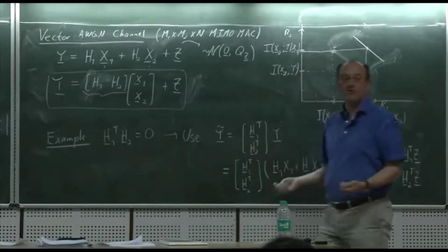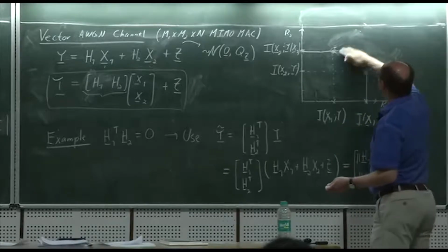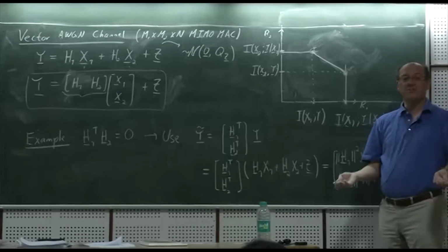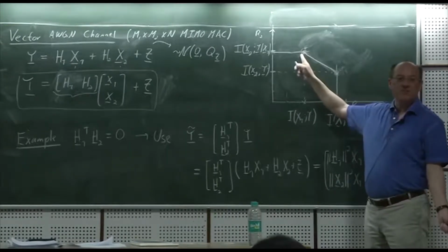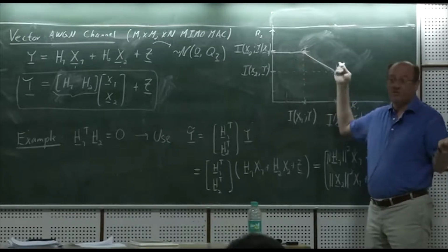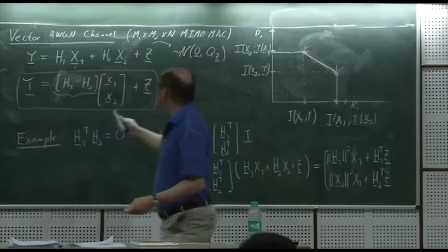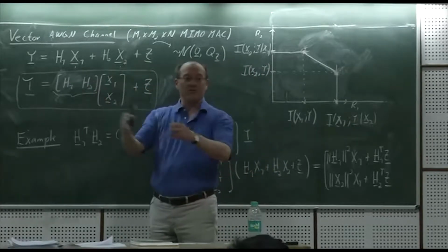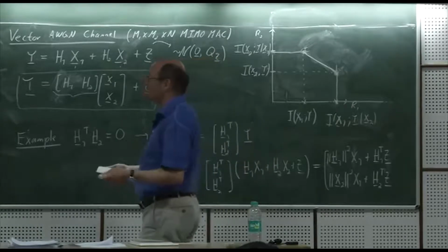Okay, so what do we do now in the general case? What's the best thing to do? So we could think about linear equalization, but suppose we use nonlinear equalization. Which method do we know and love? Successive interference cancellation, right? And that we know is even the best possible. We get corner points, right? So why not just use that? And so that's one approach we can do to get the best performance for the general H1 and H2 spatial directions approach, right? It's again the same idea. So let's talk about that briefly.